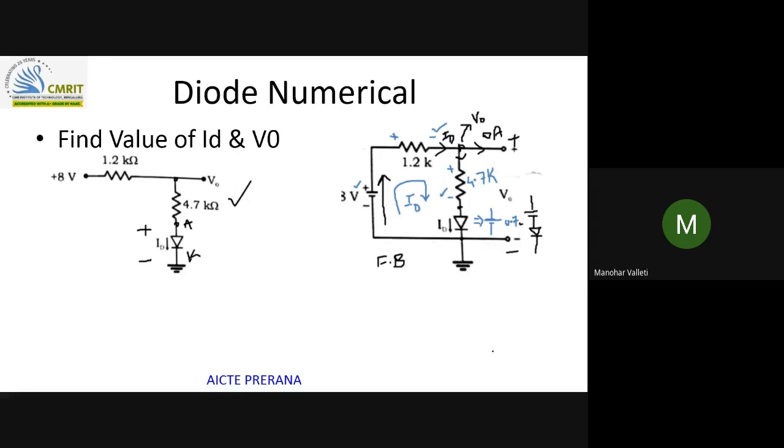Yeah, a few more problems were there. After that, we will wind up today's session, and in the next class we will see rectifiers. So we just see this was the given problem, and this is the equivalent circuit. We have to know whether this diode is forward biased or reverse biased. See, plus is there, anode is connected, so obviously the diode will be forward biased.